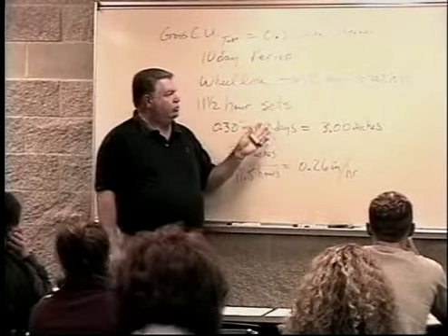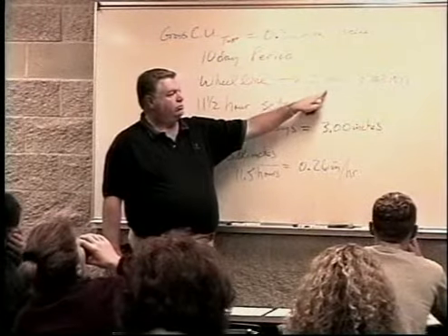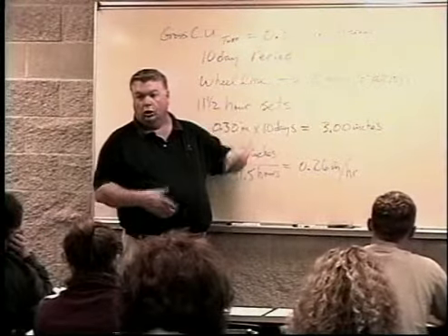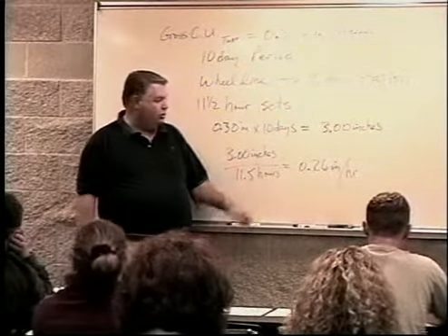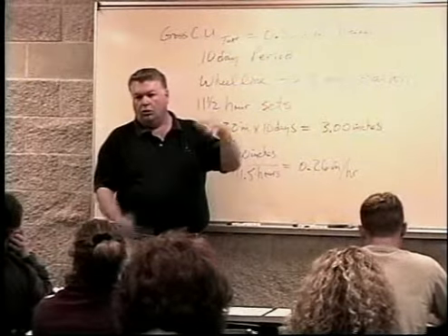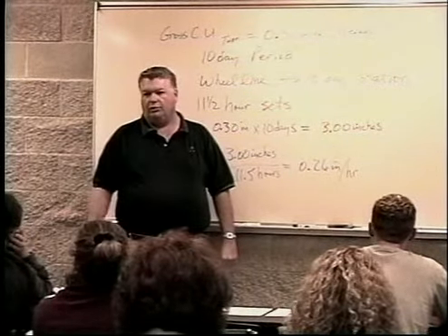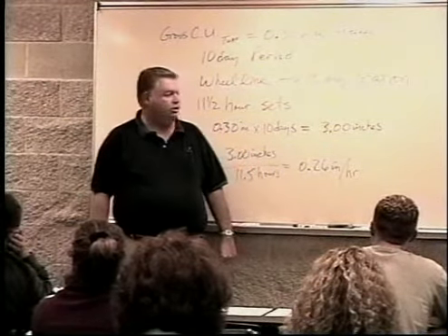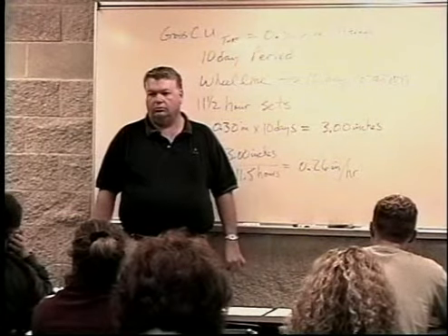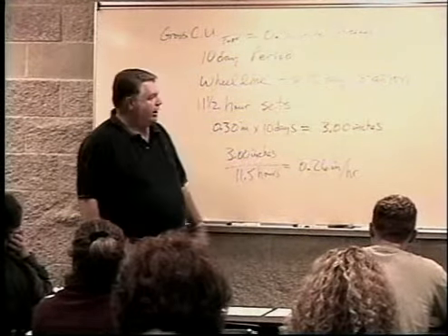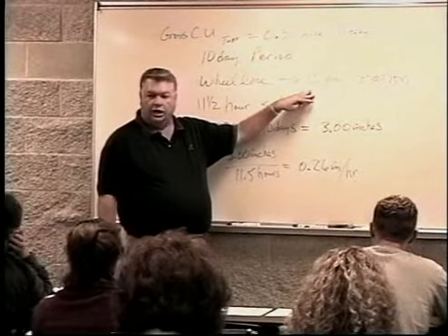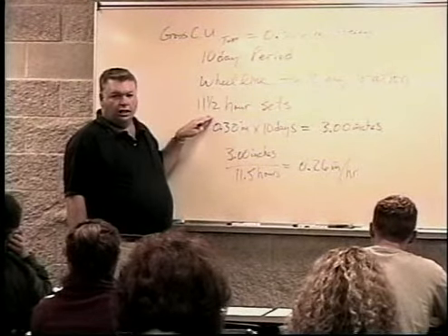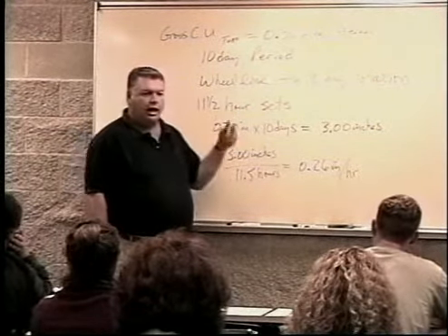The other thing is to shorten the frequency. Maybe you have to cut this back to 9 days or 8 days or 7 days and put more lines in the field. Because we're just watering one piece of the field here. We're just watering 20 valves. There might be 60 valves out in this field. You know, if you had a fair-sized field out there, you could have 3 or 4 wheel lines out there. So yeah, you can reduce the number of days in the rotation or increase the number of hours in the set. Now notice that this turned out to be a half a day.